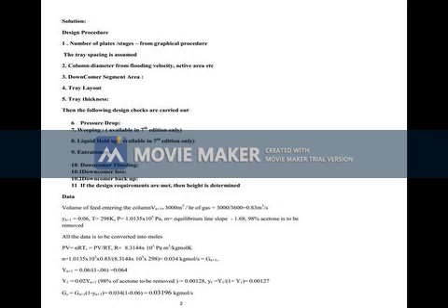So I think I have explained the problem as far as the tower is concerned. Inside the tower, the liquid will enter from the right side and flow across the cross section of the plate, and through the downcomer it will come to the next tray below.